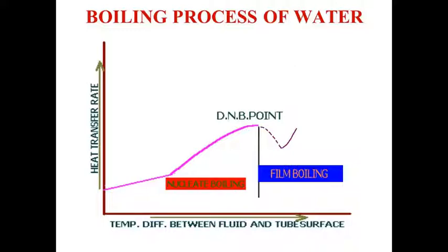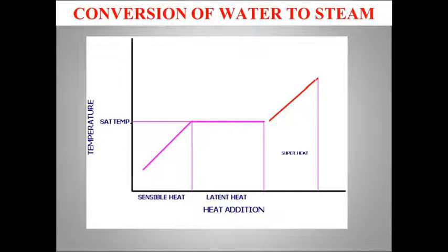As a result the actual heat transfer reduces, but the tube metal temperature difference may remain high with the bulk of the fluid. And after the entire fluid is again transformed into the vapor phase, we again find an increase in temperature with the associated increase in heat transfer rate.